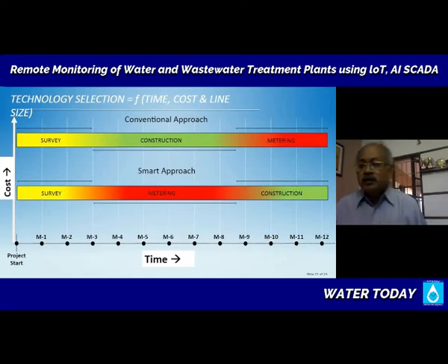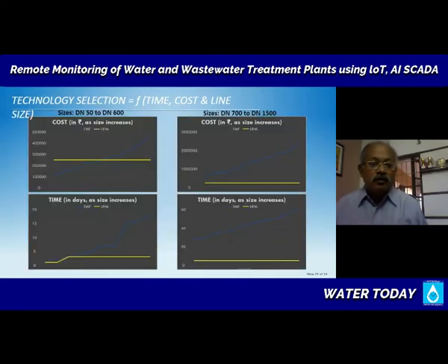because in any water improvement project, if you want to look at cost, the metering cost would be about 5% max of the entire network asset cost. So at less than 5% cost, your payback period can be very, very low. If you are smart with it, you can keep the cost down and you can bring your meters early enough. And in the months or years of data that you get early, that will justify the metering cost entirely. So this is just a quick analysis of cost and time and how to bring about a smart approach in providing metering in your water system.